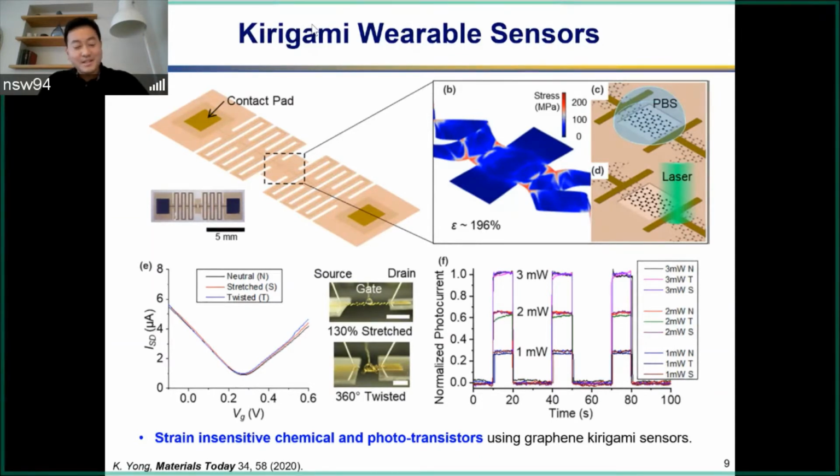Although we didn't start with this anticipation, it turns out this strain sensitivity could be quite powerful when it comes to decoupling motion artifacts. If it's a wearable sensor platform, we run around and generate these piezoresistive signals. Of course, sometimes you love that, sometimes you don't. You can handle that with signal processing, but you can also try to do that with these design components as well.